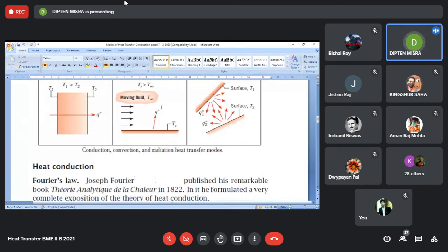So convection involves movement of the fluid adjacent to the surface. Here it is a more or less horizontal movement, while in that case it will be predominantly vertically upward movement against the direction of gravity. Now, even though the fluid is moving because of convection, we are fortunate in one sense that even though the fluid as a whole is moving, there will be one layer of fluid that will be sticking on the wall.